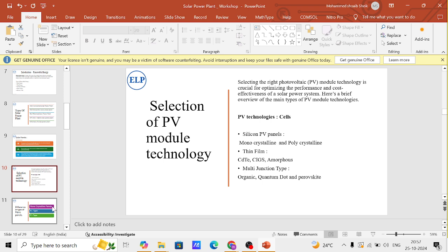So you're seeing the difference, right? If you have good sunlight but a high temperature, your solar panels will not produce that amount of energy. This is the major problem that we see in desert areas, like Saudi Arabia, Rajasthan in India, many parts of India, and Australia as well. We are seeing this kind of issue, and that's the reason monocrystalline panel technology is trying to improve to perform better in high temperature conditions. To fight with that, there is another technology as well, that is thin film solar.